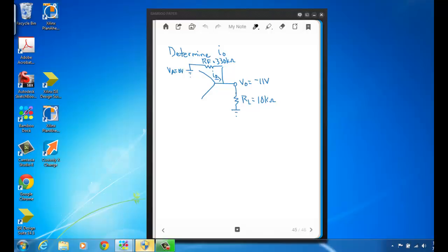And by the way, for an ideal op amp, it doesn't matter what's connected at the load as far as when you do your analysis of V out over V in. So whether we had nothing connected to V out, like when we did the analysis for the closed loop gain, or whether there's some resistor connected between V out and ground, the analysis would be the same as what you saw previously in the ideal case.